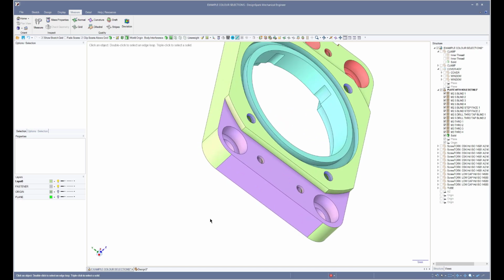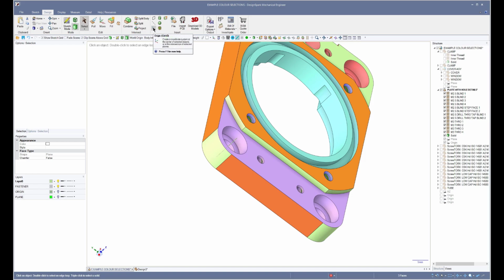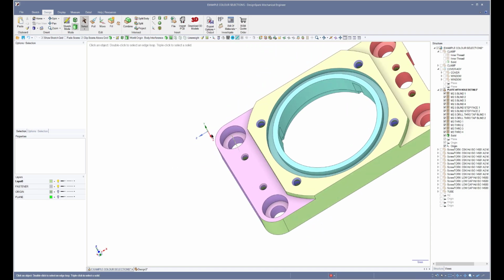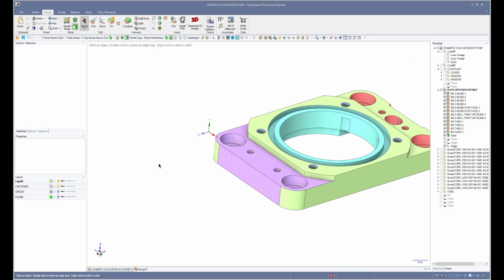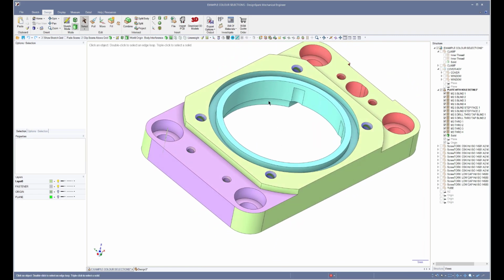You could, for instance, if you were maybe wanting measurements for NC machining and you perhaps have got this part in a vise, select this plane and another plane, and then if you go into the origin mode with those three faces selected, you can make an origin, and that puts an origin at the intersection of those three planes.